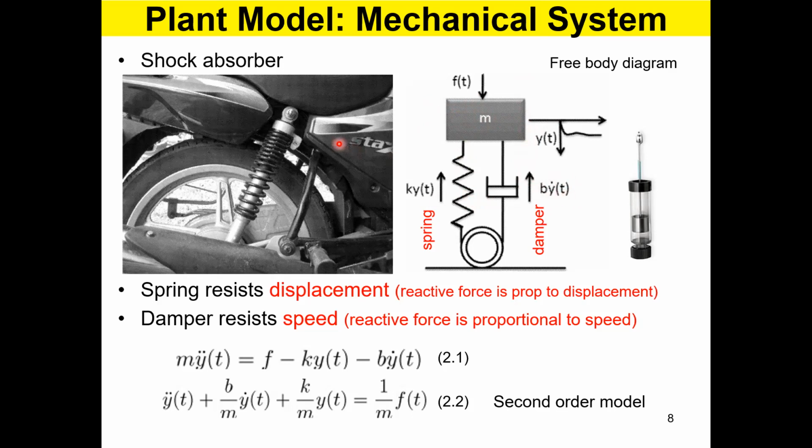Okay? So if you see this motorcycle with whatever huge load on top, when you stabilize the whole thing, you can remove the damper and nothing will happen. Damper is not taking any load when the system has no motion. When the motions are settled down, when the velocity is zero, damper is just sitting there. It is elongated, the length is different, but it can stay there without producing any force. It produces the force only when it is moving. It can stay at this level or that level without producing any force. The moment you try to move it up or down, then it produces a force. See the equation, y dot.